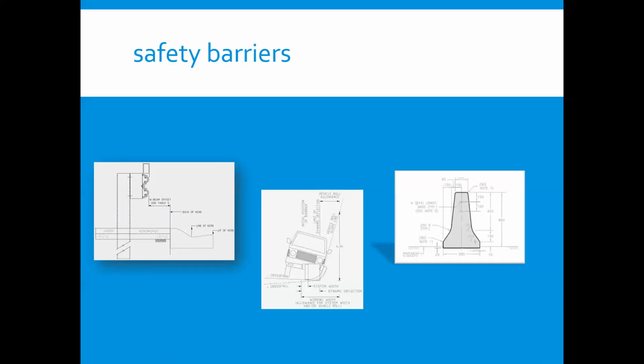The wire rope barrier works through the high tension cables. An errant vehicle knocks out the supporting post and the rope deflects with the vehicle before directing it back towards the direction of traffic. Curb and channels should not be placed in front of the safety barrier. The curb and channel is essential.